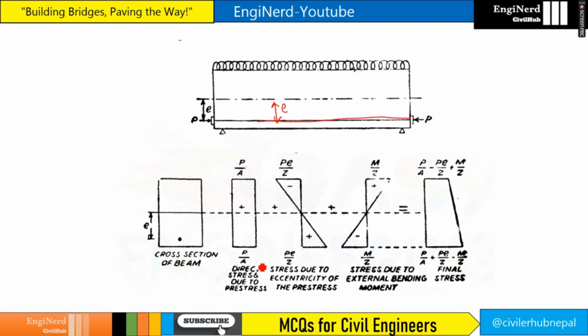Now let's see, due to prestress it's uniform, right? P by A, and due to eccentricity of the prestress it's P E by Z, minus here and plus here, and due to external bending moment, plus here and minus here. So at the top it is decreased by what? PE by Z, right?